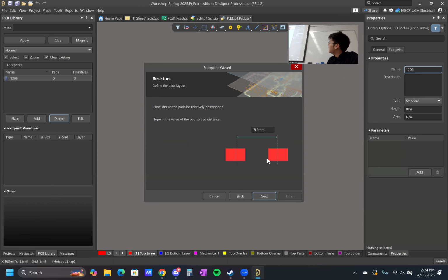Pretty good. And what is the distance between the two pads? Now, what they gave us was the distance from one pad to the center. So do some math in your head. You've got to double this value to get the distance between the two pads. So this would be 2.8. And you'll notice the diagram has hatch marks to show exactly what dimension you're measuring.